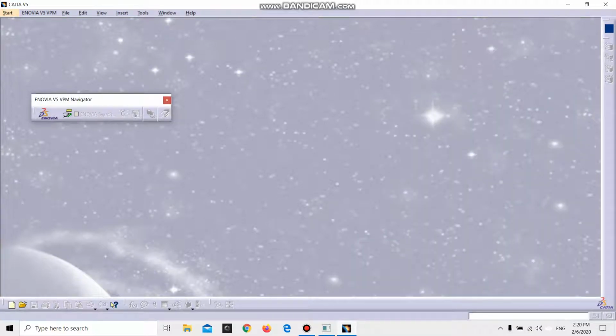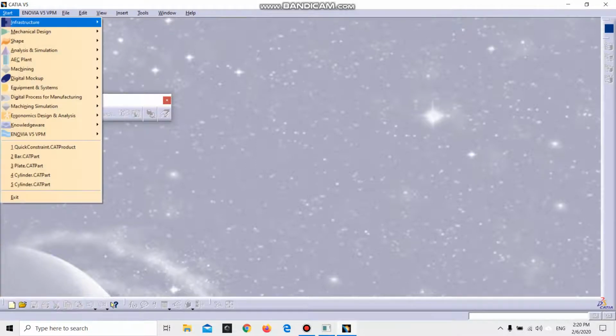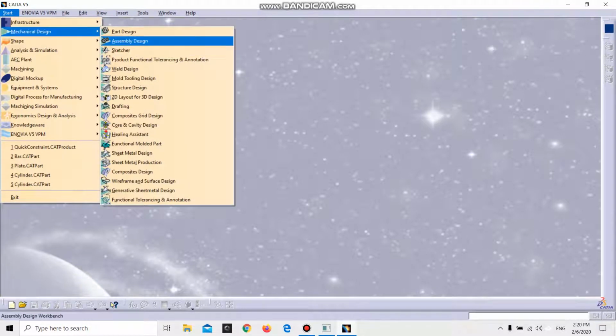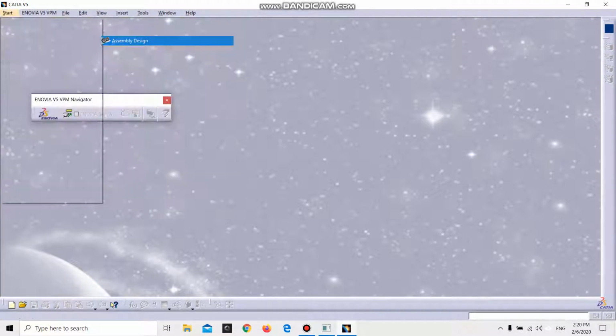In this short tutorial video, I'm going to show you how to do the assembly using the CATIA V5. Before you begin, you need to get into the Assembly Workbench. So drag your mouse to the start, go to the Mechanical Design and click on the Assembly Design.